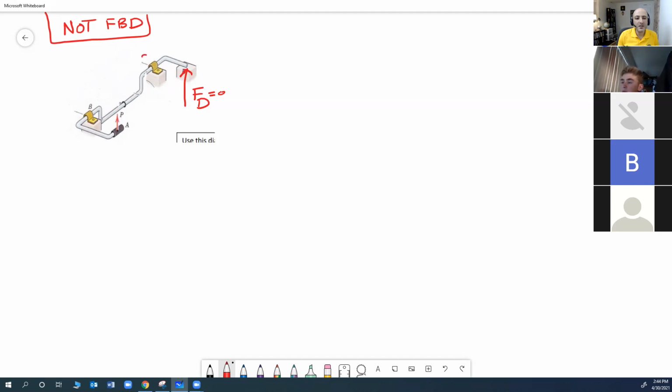So bearing C and bearing B, I have only axial forces, no moment. So I'm going to have CY and I'm going to have CX. By the way, this XYZ was just like this. This was X, this was Y, and this one was Z. B, same way. I'm going to put a BY and I'm going to put a BZ. No moment. You have two CYs on the C. Oh, yes, CY. One of them needs to be CZ. This is CZ. Thank you.